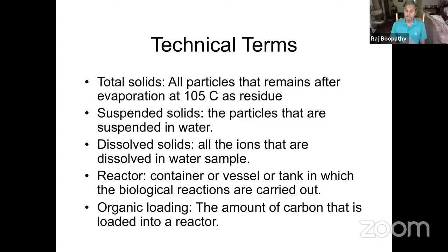Suspended solids are the particulate matter that is suspended in water, so you filter the sample, and the solid that's filtered out was suspended in the water, right? That is called suspended solid. If you know the total solid and suspended solids, the difference is dissolved solid. The dissolved solid is mostly the ions in the water sample, okay?